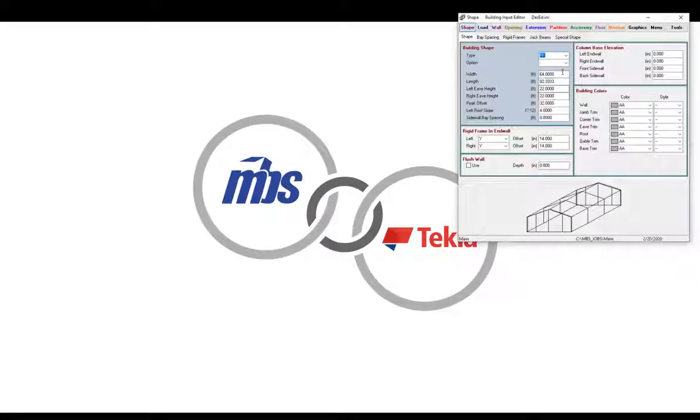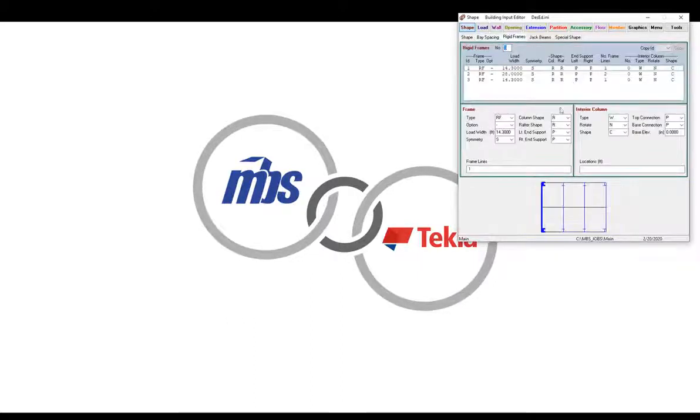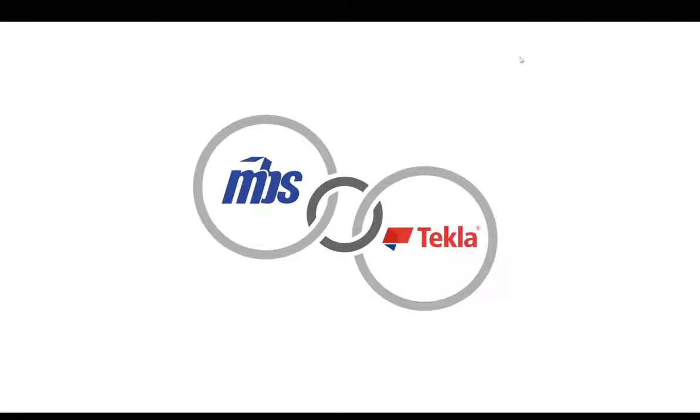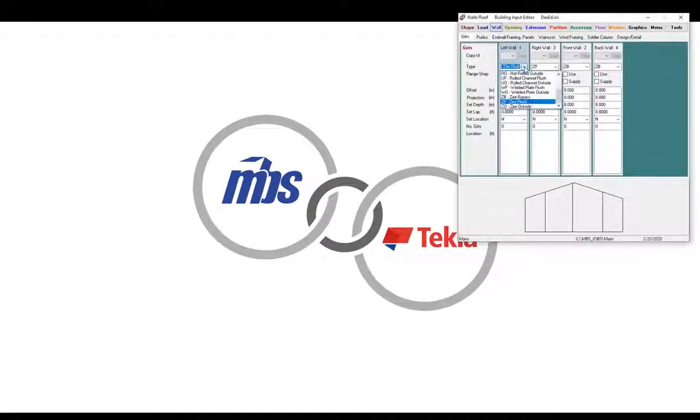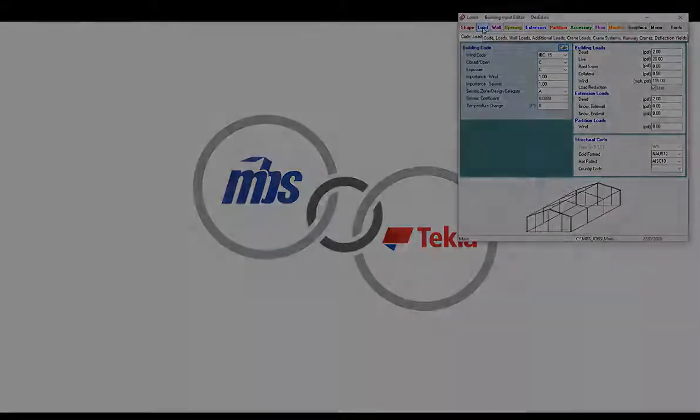This example of the main part of our building includes the width and the height, our eave heights and roof slopes. You can also enter things like your column base elevations. In here we can define the base spacings, and rigid frame locations and types. You can also define things like openings, your roof purlins, your wall girts, types, spaces, and then finally we can apply the loads using your local building codes.